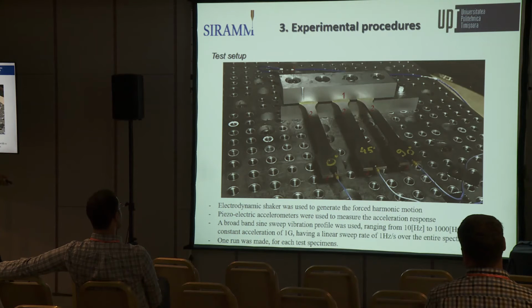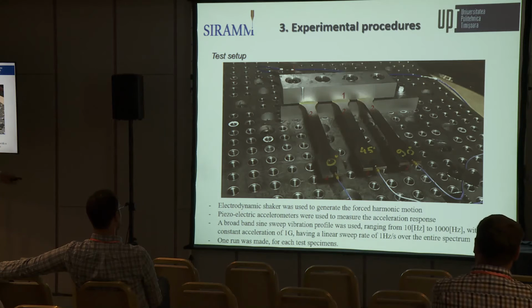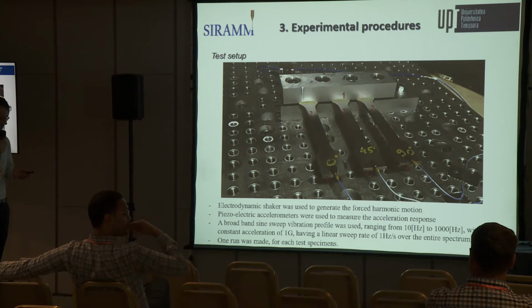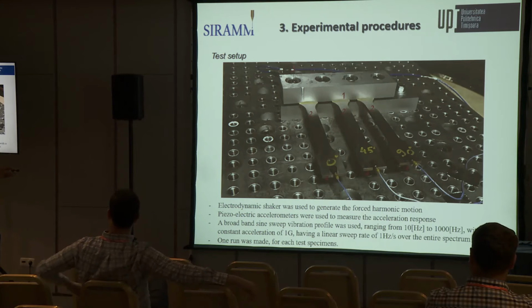We use an electrodynamic shaker to generate the harmonic force motion to excite the specimens. Piezoelectric accelerometers were used to measure the acceleration response, and a broadband sweep vibration profile was used, ranging from 10 to 1000 Hertz, with a constant acceleration of 1 g, having a linear sweep rate of 1 Hertz per second over the entire spectrum. One run was done for every specimen.